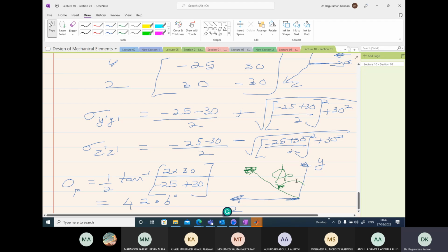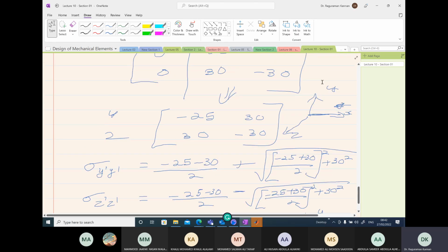Now which direction of the angle is positive or negative depends upon how you draw the y and z axis. Be very, very careful. If you have the y axis here and the z axis up here, then it will be anti-clockwise. But if you let's assume this is the y axis and this is the z axis, then clockwise will be positive. So you need to know which one is positive or negative. How do you figure out in 3D whether an angle is positive or negative? Based upon your right hand rule on 3D axis.